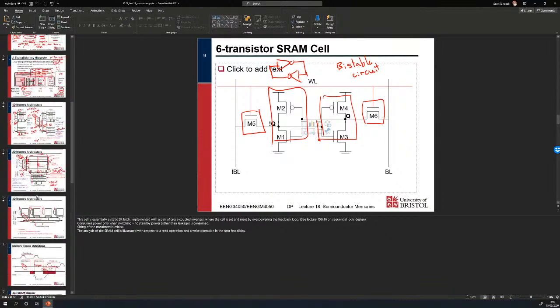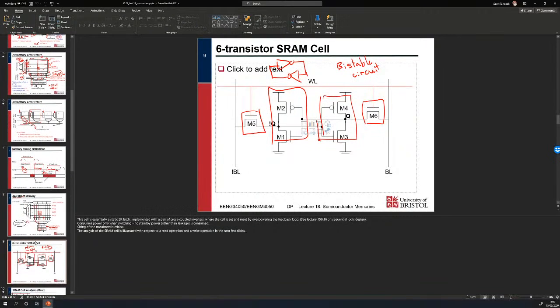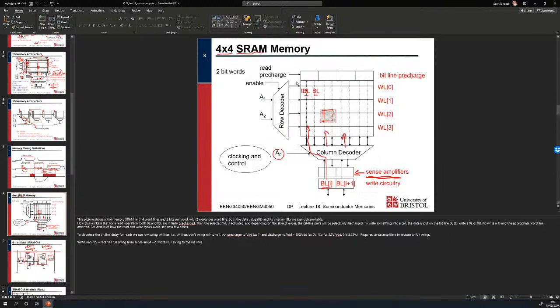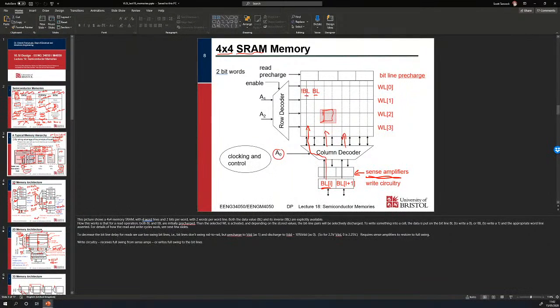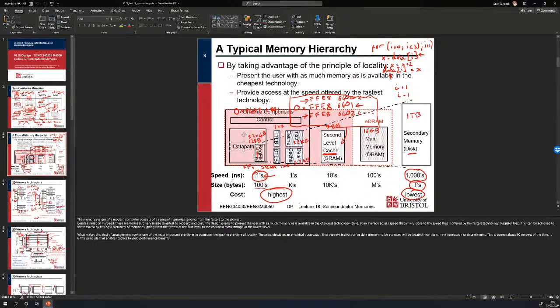We don't have to have the sense amplifiers, and also we can access all the flip-flops at one time, as opposed to only being able to address one word. So there are multiple reasons why flip-flops are used inside the data path, in the reg file, and also inside some of the control logic.